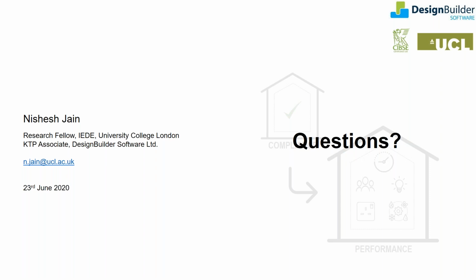If you're doing a very building-specific study, have those things in your hand and then discuss it with the potential occupant if you have access to them, or the owners or the managers, and vet it: is this the typical pattern? And once you have identified the typical pattern, the main point would be to try to do a sensitivity and uncertainty analysis on that. Use a low, so have three variations of the same, and then see how susceptible the building is to that occupancy variation.